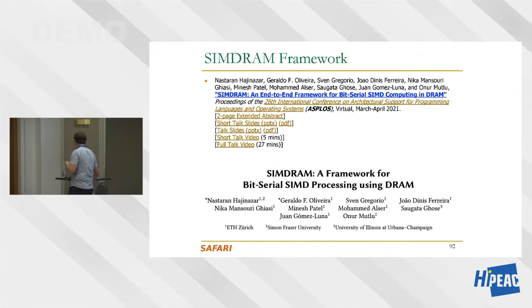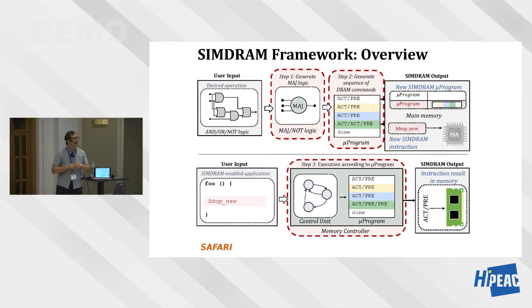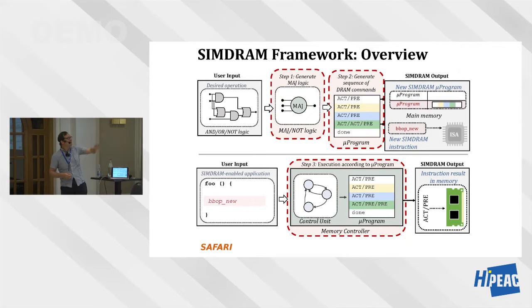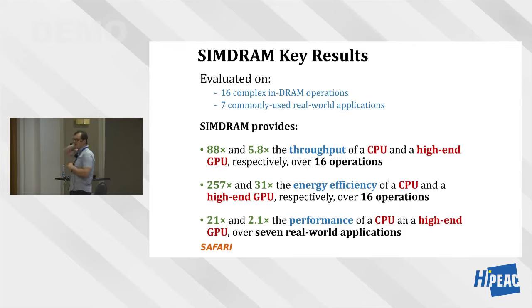Okay, so these are the papers. This is where we stopped last time. I introduced the SIMDRAM framework, which essentially takes these majority and NOT operations in DRAM and makes them usable by anything, essentially. Whatever the programmer or the ISA designer envisions, they can express the operations using this sort of circuitry, and then we can optimize it, and then we can associate an instruction with it that when it's executed, it calls a microprogram that executes on the memory controller. And the memory controller basically uses these RowClone and Ambit commands, triple row activation commands, to execute the instruction. And we see significant benefits out of this.